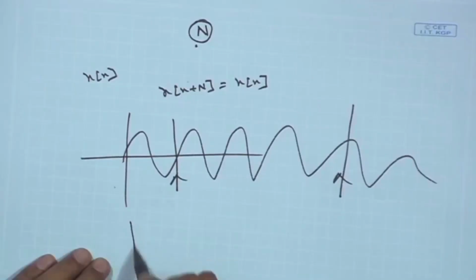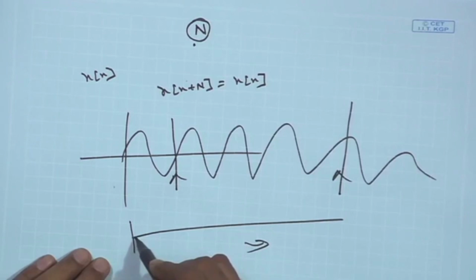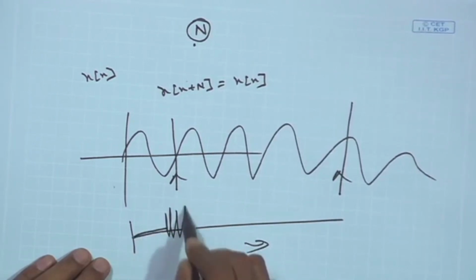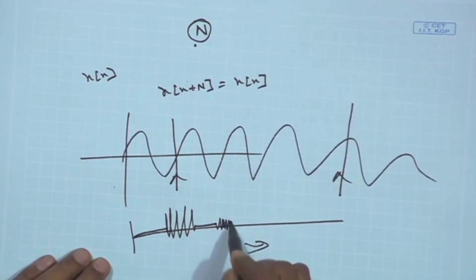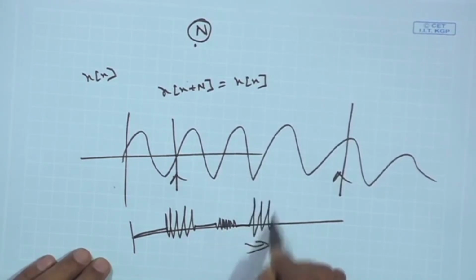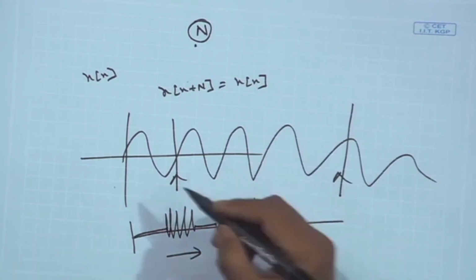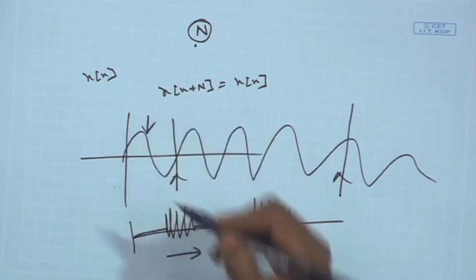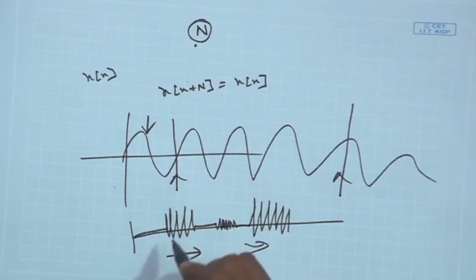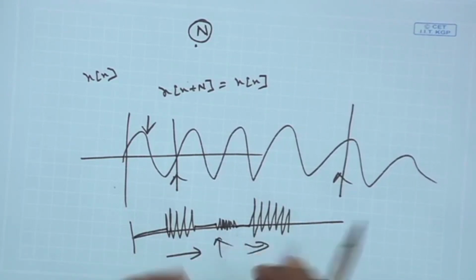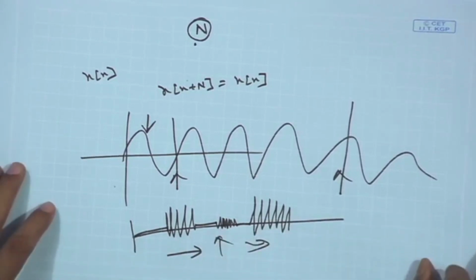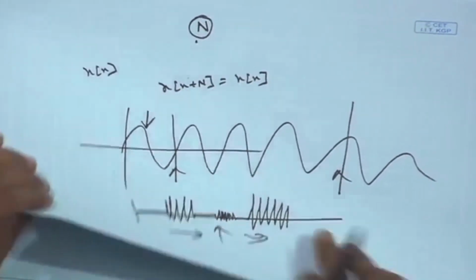Now, say the speech signal. If I say a sentence, along the time the signal properties vary, sometime it is silent, sometime it is voice, sometime it is silent, sometime it is friction, then maybe silence, then maybe voice. So, I can say along the time signal changes its property. So, it is a time varying signal. Later on you learn that signal processing algorithms are applied on a stationary signal. So, I have to consider how I make the speech signal stationary. Those kind of considerations we will take. Okay. So, this is stationary and non-stationary signal.